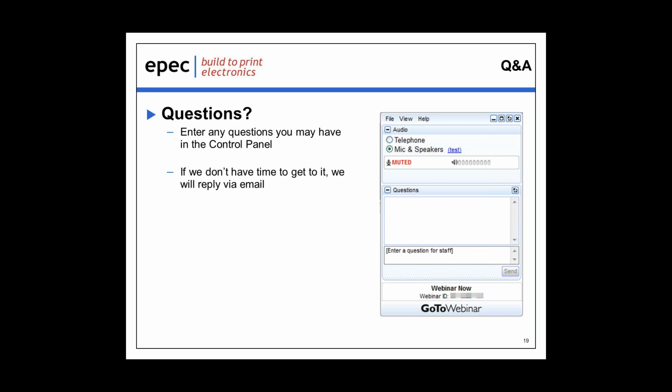That's a fairly difficult question to answer. I can give a general statement. If you look at a PVC, it's probably the lowest costing material out there. Then as you go up, TPEs, TPUs become more expensive. Then when you get into fluoropolymers, those are the most expensive. However, within a given family, such as PVC, there could be some formulations that are quite higher than a standard PVC because of the amount of additives they put into the PVC to obtain a certain flame package or to obtain a certain flexibility at a certain rating. But again, general rule of thumb, as you start to go up from the general to the riser to the platinum, price will increase accordingly.